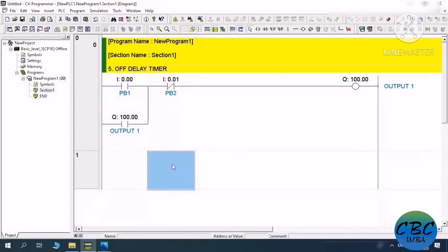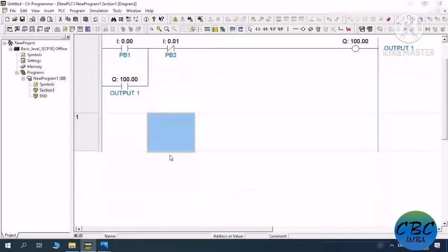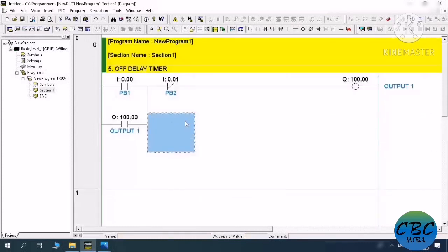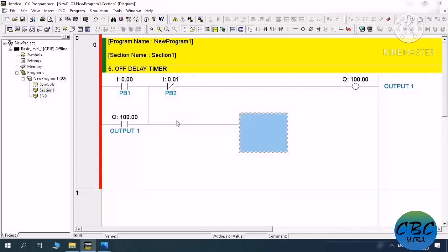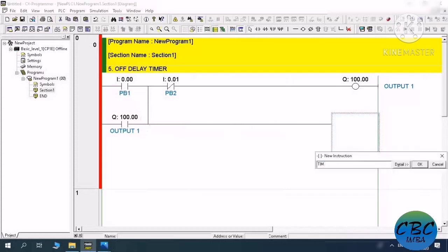Okay, so the timer can also be created in this kind of shorting rung. We can input this to the line of this timer, just type I, then TIM 0, for example, then let's say 5 seconds for the off delay, then enter, say this timer 0.